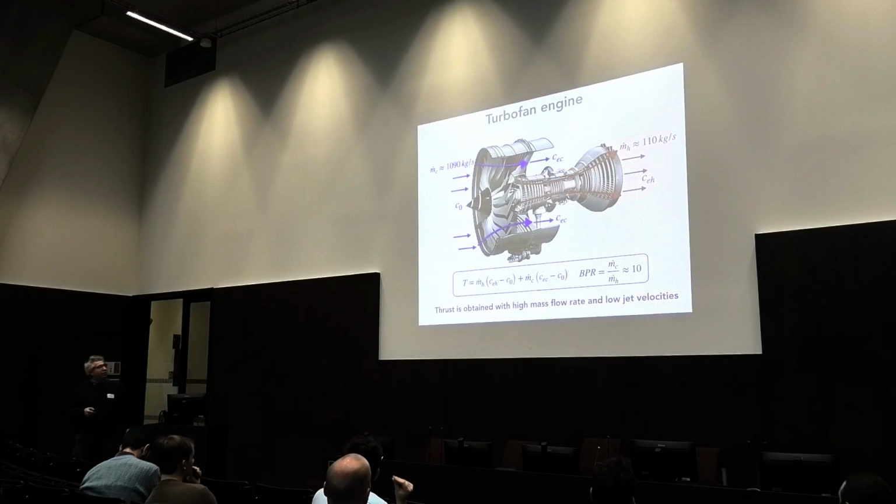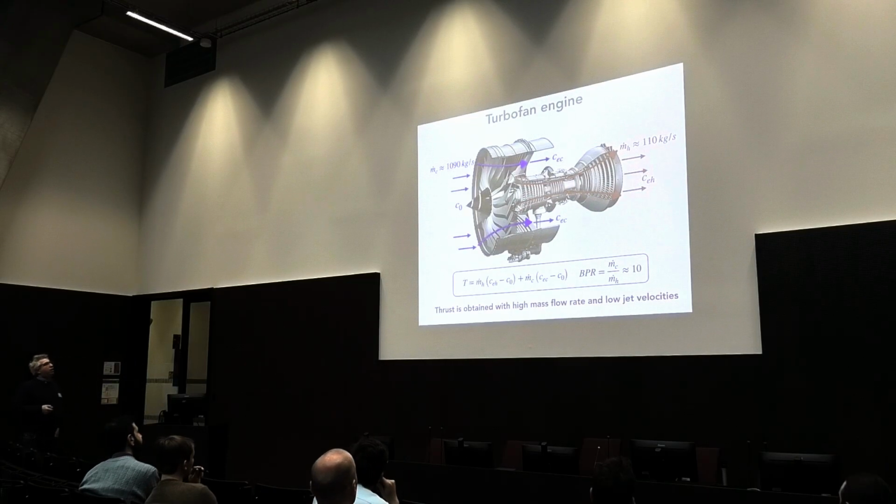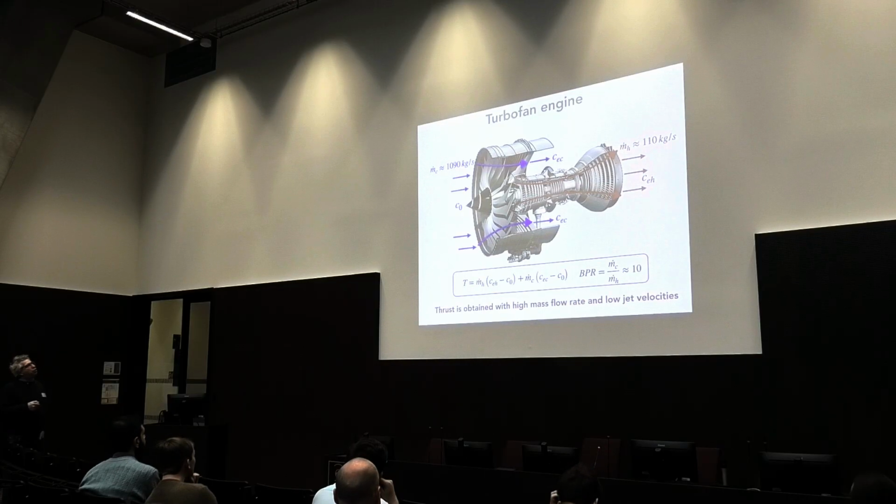Now if we look at a modern aircraft engine architecture, it is quite different because we will split the incoming air flux. So typically you enter about 1,200 kilograms of air each second, meaning that if you have a building of 10 meters by 10 meters by 10 meters in the 3 dimensions, you are able to suck all the air in this building in only 1 second.